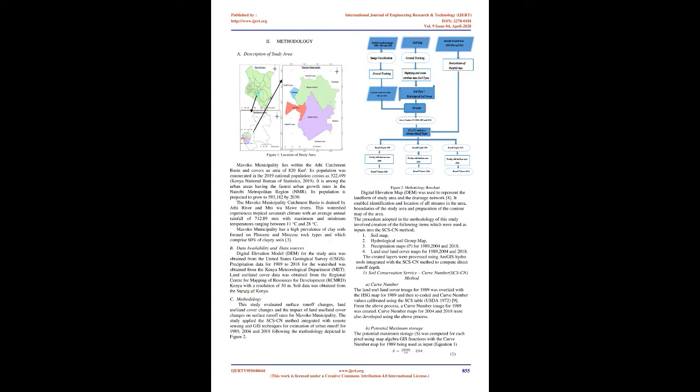Among all hydrologic models, the SCS-CN method stands out as the most widely used empirical model for computing the depth and volume of surface runoff. The SCS-CN was developed by Ogrosky and Mockus in 1957, though it has undergone major advances since then. 5. This method not only considers climatic factors but also watershed characteristics such as soil type, slope of the land, hydrological soil condition, HSC, antecedent moisture content, AMC, and land use/land cover type. 6.